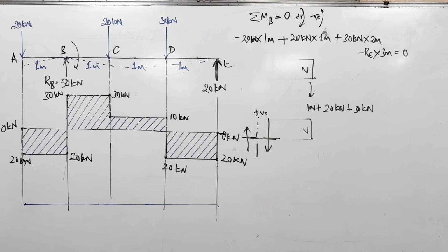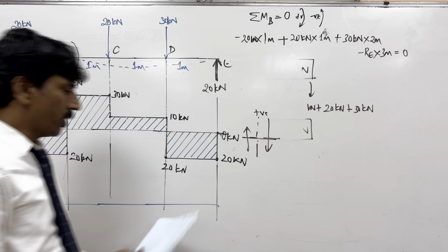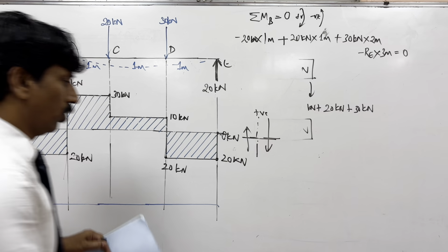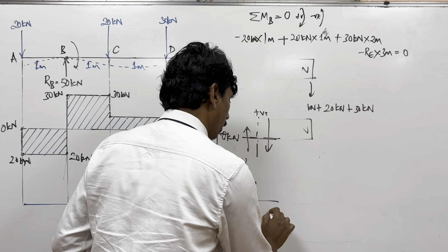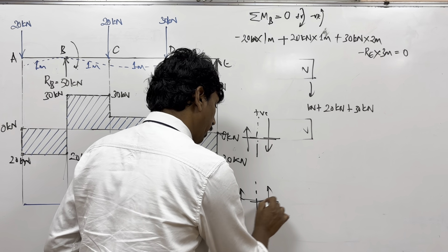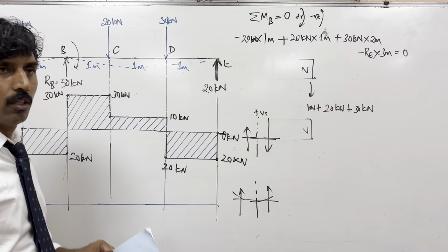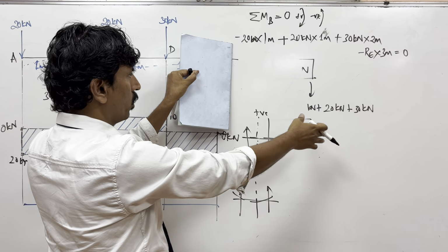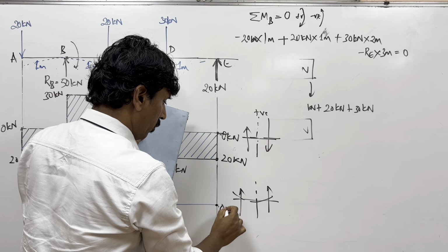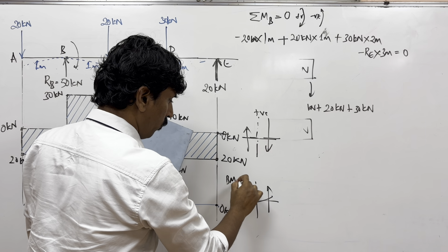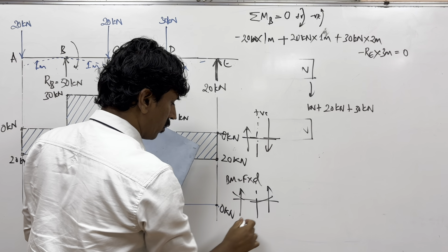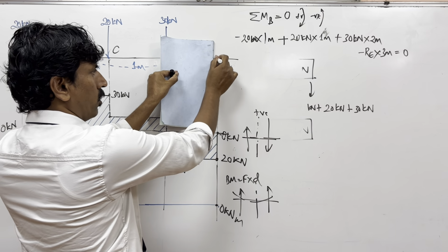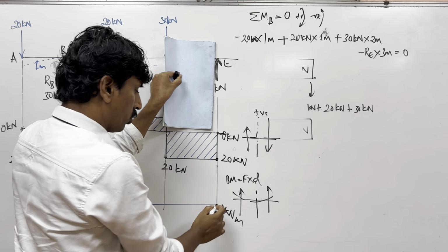Okay. Now, what is the convention for bending moment? So, if it is the beam, upwards positive on both sides, which will actually create sagging. Okay. So here, if I continue this beam, there are no forces here, no distance. So bending moment is zero. Bending moment is force into distance. Force is kilonewton, distance is meter. It is 0 kilonewton meter. And then suddenly here, there's a force, but is there any distance? No, sir. No distance, so it is still zero.